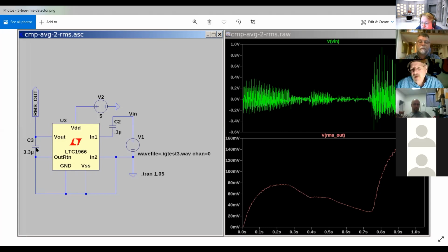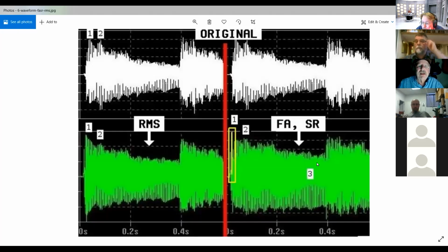If that's too small, it's going to respond a lot faster, but you get distortion at low frequencies. If it's too long, you're going to start getting ducking because the release time is going to be too slow. Even RMS, while it theoretically and mathematically does not have an attack and a release time, in real life is going to have, I guess we'll call it, response time.